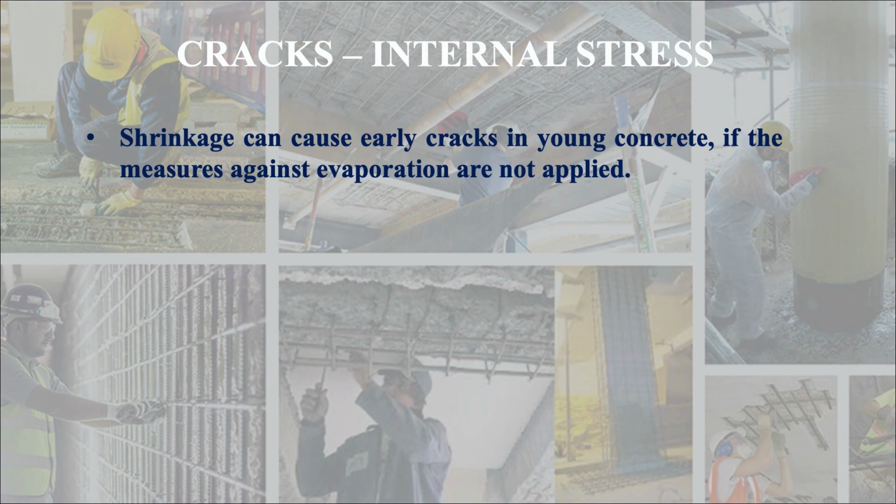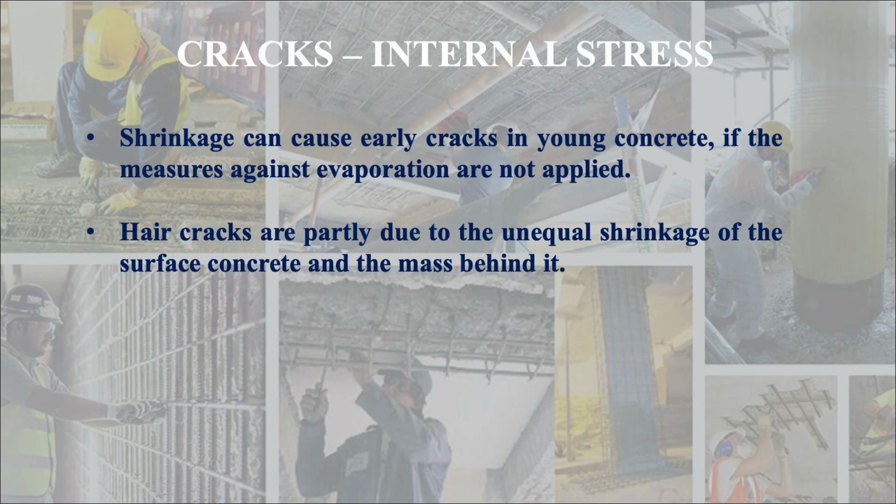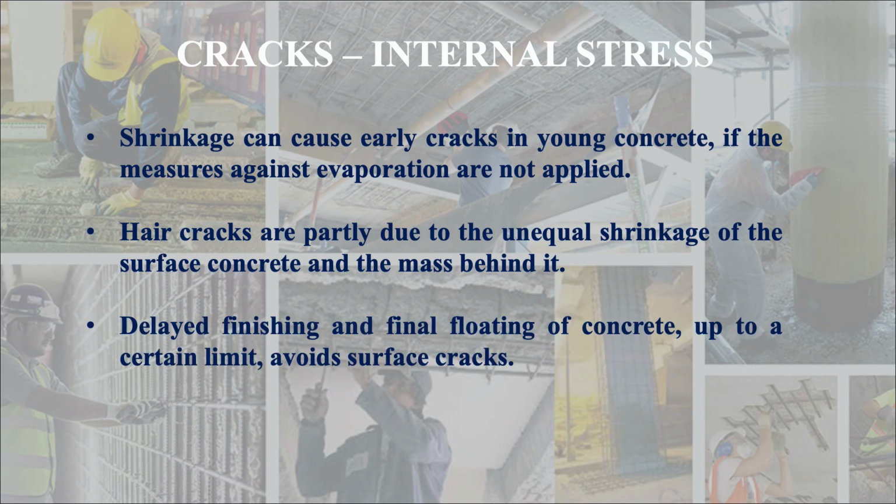Shrinkage can cause early cracks in young concrete if the measures against evaporation are not applied. Here cracks are partly due to the unequal shrinkage of the surface concrete and the mass behind it. Delayed finishing and final floating of concrete up to a certain limit avoids surface cracks.